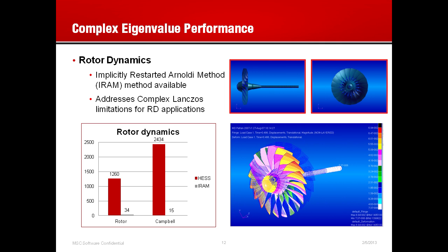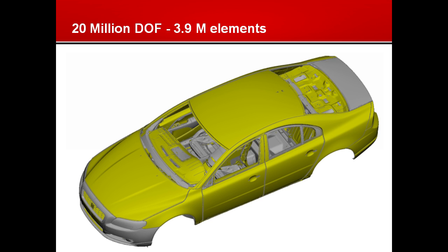So not only doing traditional real eigenvalue analysis of symmetric systems, but also problems that lead to complex eigenvalue analysis, such as rotor dynamics, such as perhaps problems that have damping or problems that involve friction. We also have improved the numerical techniques to solve these problems as well.